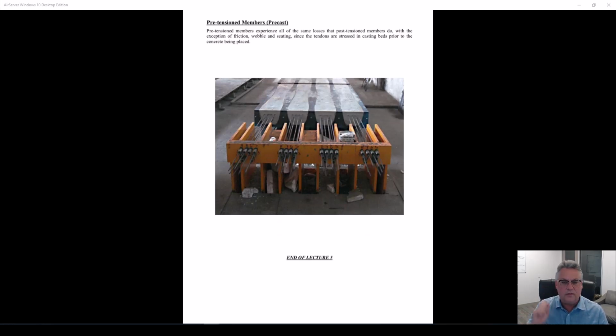And by the way, the least amount of pre-stressing will also be the least amount of headaches too, because all the other effects, the effects of the building shrinking in, shortening in, pulling on the columns, pulling on the walls, pulling on interior partition walls, those problems are minimized if you minimize the post-tensioning. So the game that gets played, and they pay us for doing it, is to figure out how to satisfy every part of the code, standard of care, and practice while putting in the least amount of pre-stressing in the building. That's the best design, and I almost always ask that question somewhere, particularly at UCLA on the final.